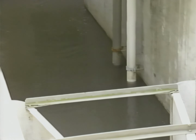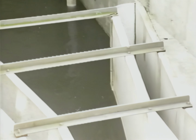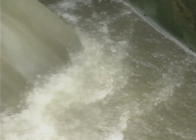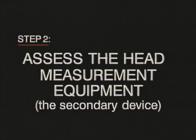Finally, check to see that both the upstream and downstream channels of the flume are free of debris and deposits. Deposits could mean the flume is sized too large or it is set incorrectly in the channel. Remember, one of the advantages of a properly operating flume is that it is self-cleaning. If there is an accumulation of debris or scaling, there's a problem. That about covers the inspection of the primary device or Parshall Flume itself. But at many plants, the flow measurement system includes secondary devices, such as ultrasonic transducers, bubblers, and floats.